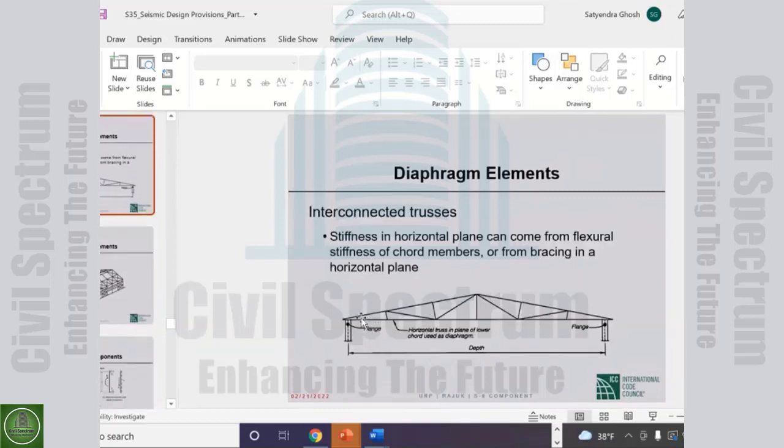Yeah, if you can imagine on this horizontal plane, into the screen, horizontal bracing would serve quite well as diaphragm. As I said, we saw this in and around Santiago, Chile. The industrial buildings were many of them that way. That was their diaphragm.